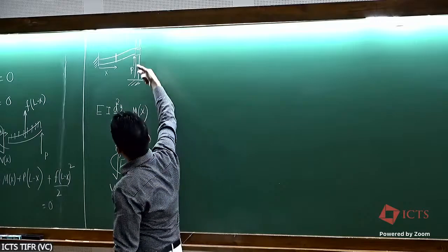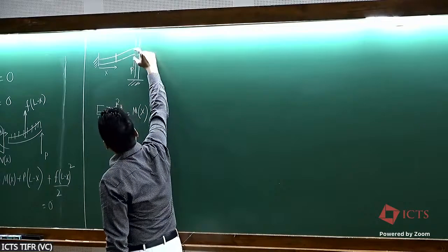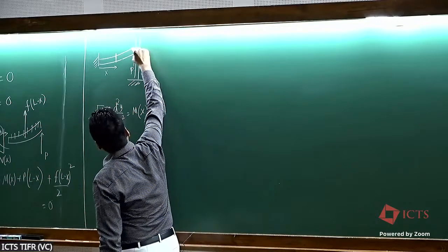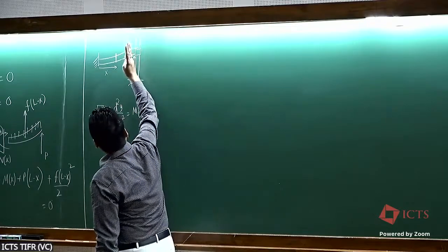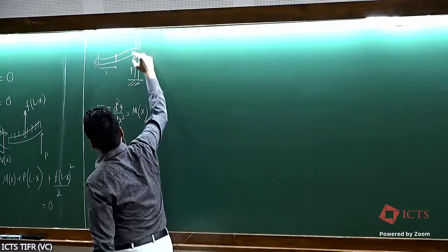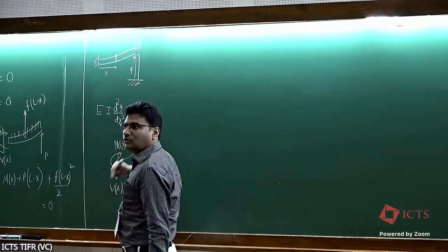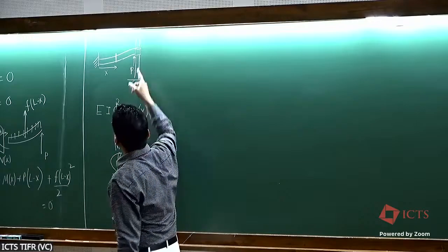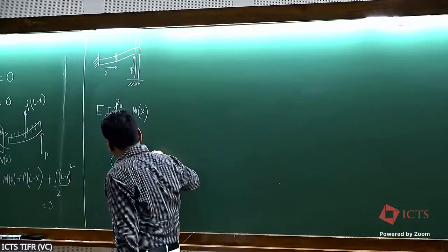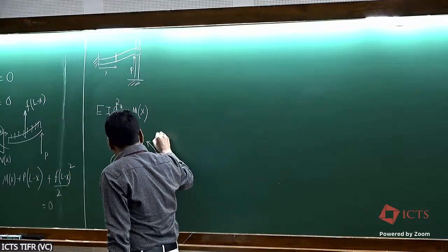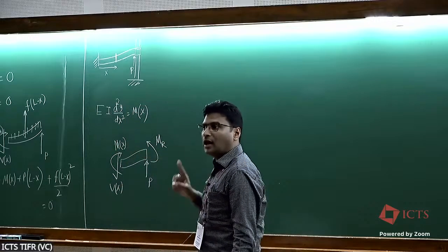Because as you see here, it is fixed on this rod. So the whole cross section here is not allowed to rotate. It has to go as a vertical cross section up and down. So the cross section is not allowed to rotate, which means there will be a reaction moment from the rod. So there will be some MR, R for reaction, an unknown reaction moment here.